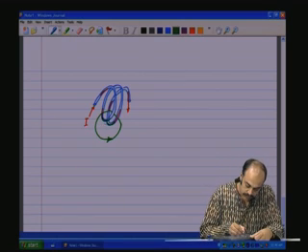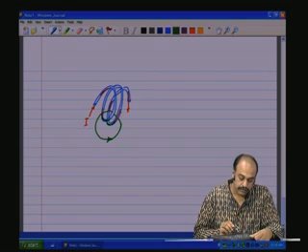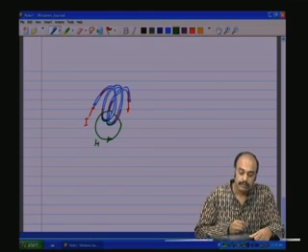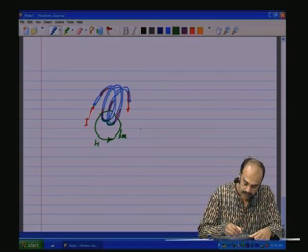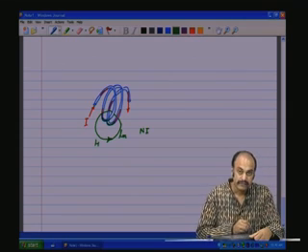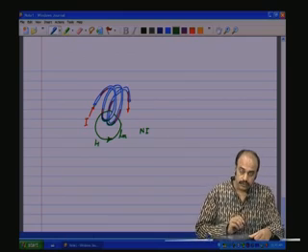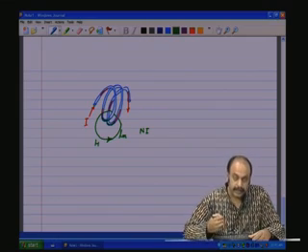So if there are two, or if there are n such conductors, each carrying current I in this coil, that is causing a field of intensity H to be created, and on integrating this H around the magnetic path length Lm, it will give you Ni, depending upon how many turns you have put. So this is the principle in which Ni, the magnetomotive force, is created.